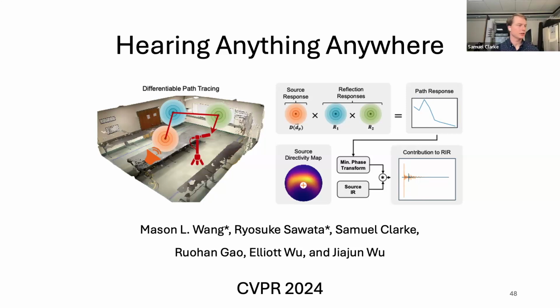Yeah, those are a couple of great questions. You're right. I talked earlier about how when you have a fork striking a mug, you're hearing the sound of a fork, but I didn't explain how we filter out the hammer. First of all, the impact hammer is very small. The head of the hammer is small enough that the frequencies of its modes are actually outside the realm of human hearing.